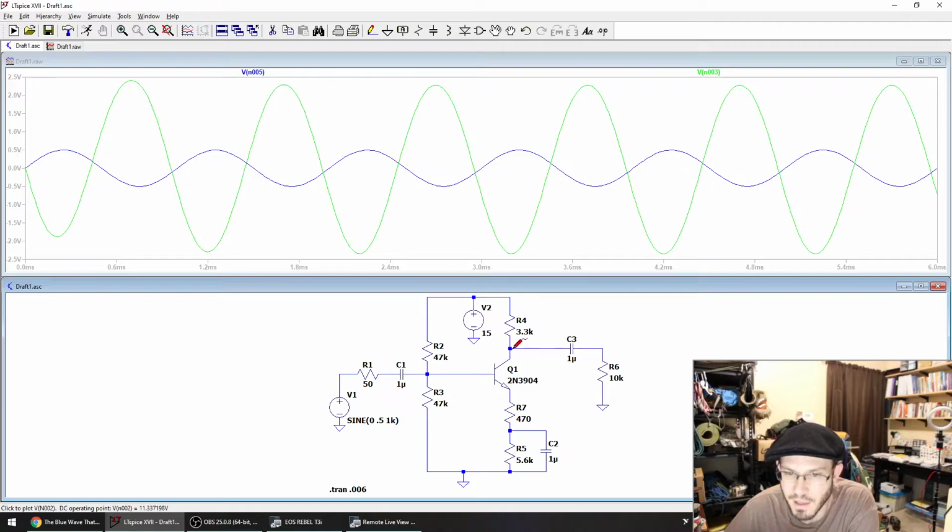We're taking our signal from the top of this BJT over here. So as current goes through here and as it increases, the voltage goes up as it's applied here. The current through here increases, the voltage goes up across VCE, and as the voltage across VCE gets larger, this gets smaller. So you get an inversely proportional relationship. Okay. And you could just go back to any of the lecture videos for the clarification on that. I think I hit this point about 2 or 3 lectures ago. I spent about 10 minutes explaining that. Okay, so inverted, 180 degrees out of phase.